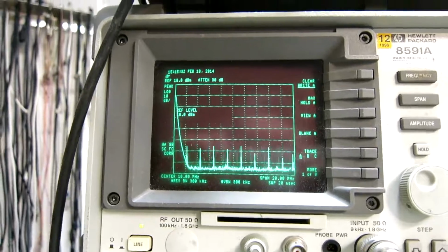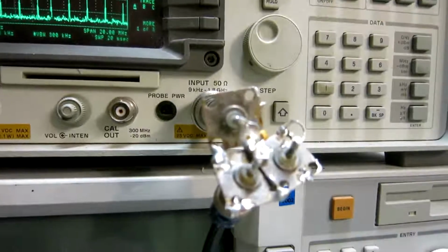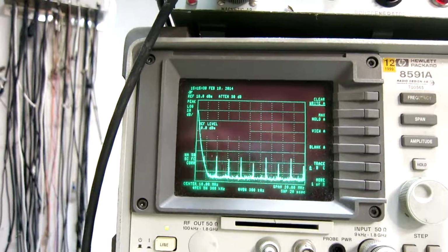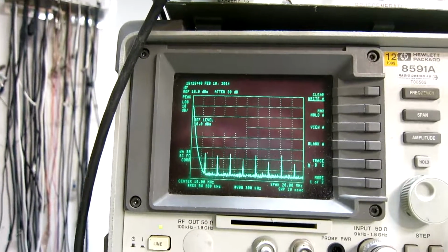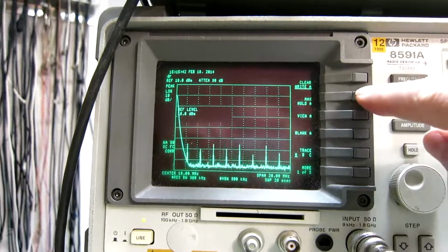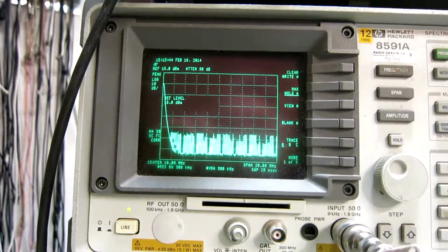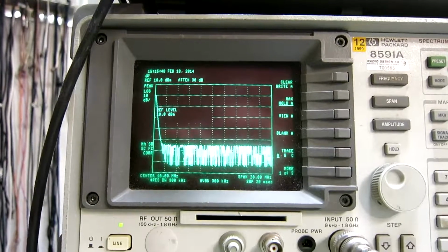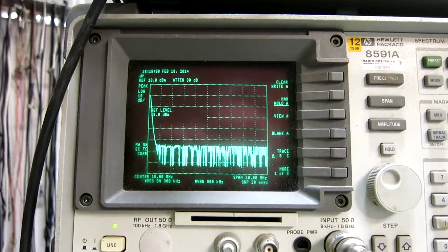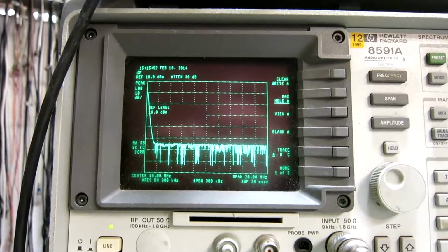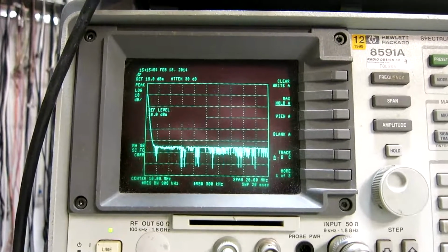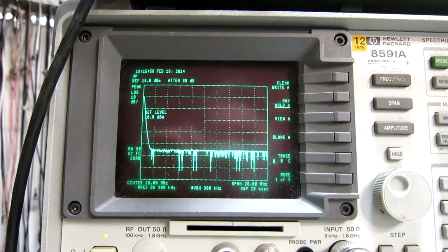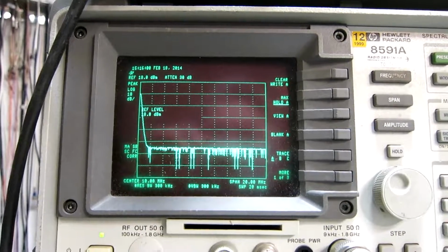With a capacitor in series like that, the spectrum is now more or less flat. Can press max hold again. The signal is quite a bit weaker, but it is flat to within a tenth of a dB or something, more or less from 2 MHz to 20 MHz.